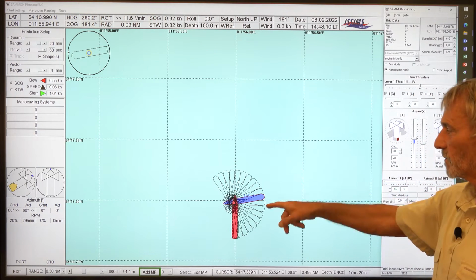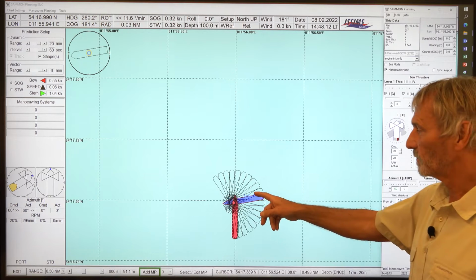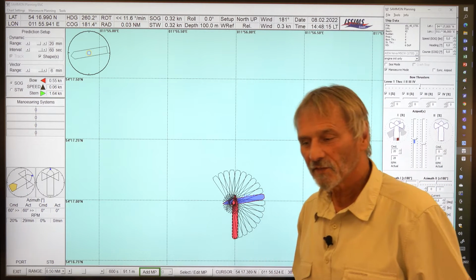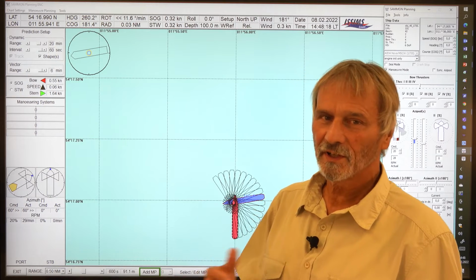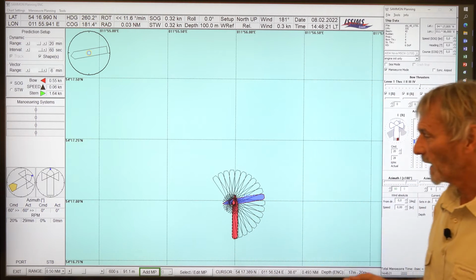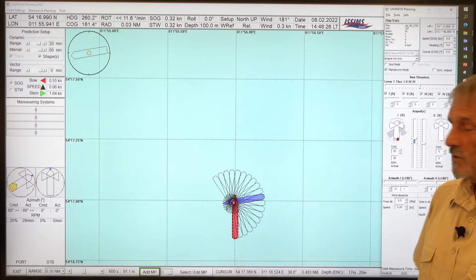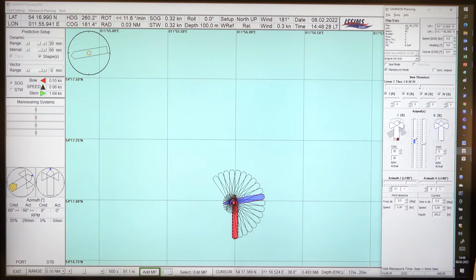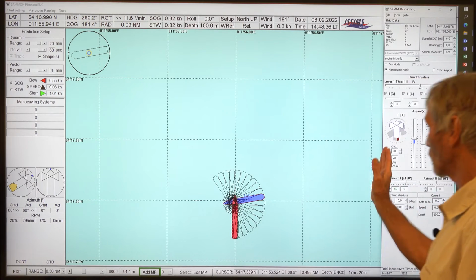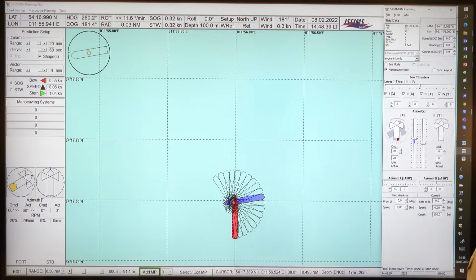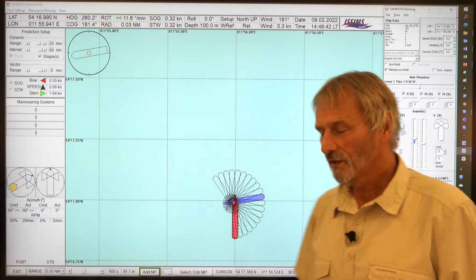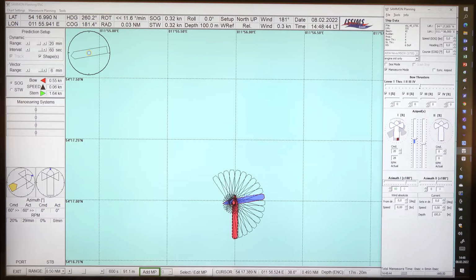The power here at the pod is so big that the drift angle gets so big that there's no lift force anymore. It's only like a resistance. And so the ship is turning nearly on the spot. So this is, for instance, a sample where you can immediately see the resulting pod force is pointing to 60 degrees, and we go with 20% ahead. We could also bring it to 120 or others.